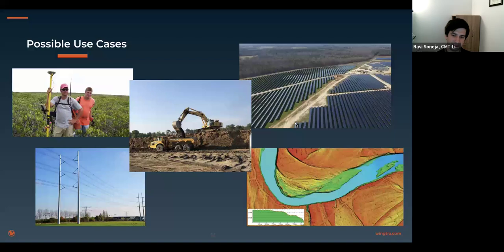Stepping back to the manned aircraft world, when we did countywide mapping projects, like I said, we like to fly LiDAR in the fall and early winter before the snow gets on the ground. If you end up in the spring with snow on the ground, it tends to map that vegetation down. So at least you're getting something that resembles a ground surface, but it's not quite there.